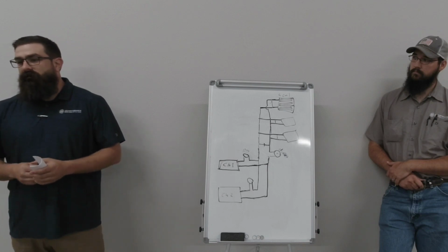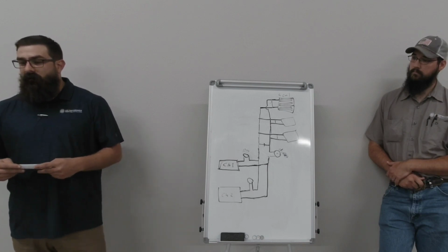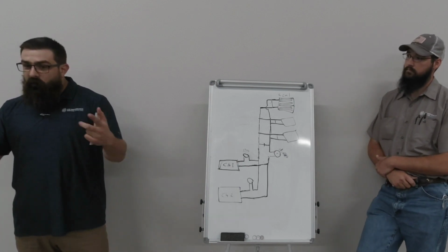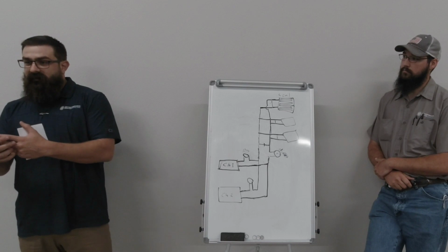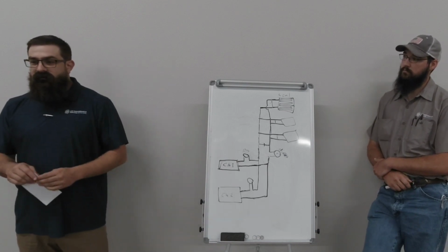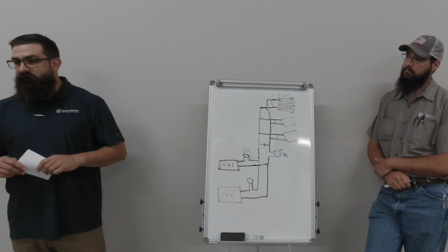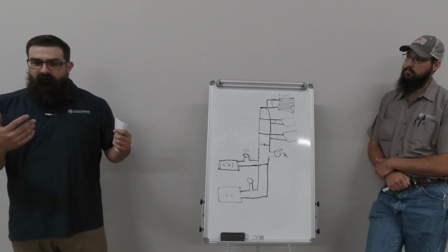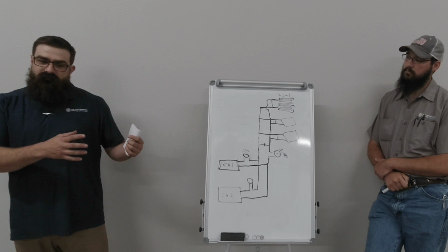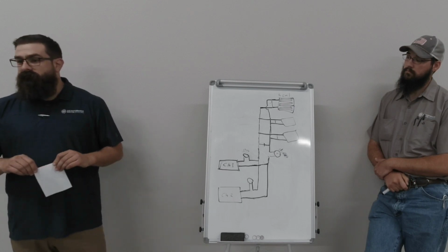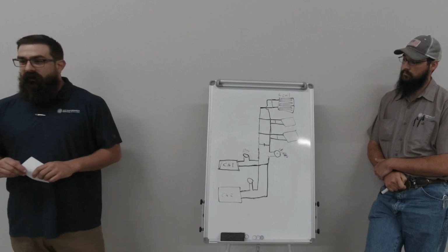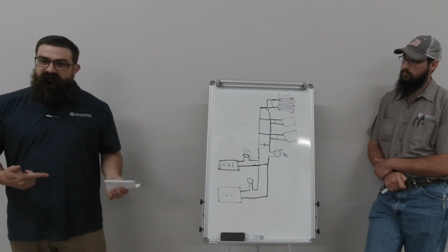You can do it with steam and create hot water by pushing steam through it, and then the lukewarm water becomes hot by sucking heat out of the steam. You can use condenser water to isolate an open loop from a chiller. So if you've got a chiller you don't want to push an open loop system through, people put heat exchangers on them. That way you can have an open tower with a closed chiller.